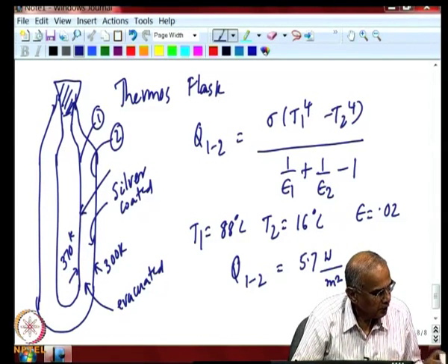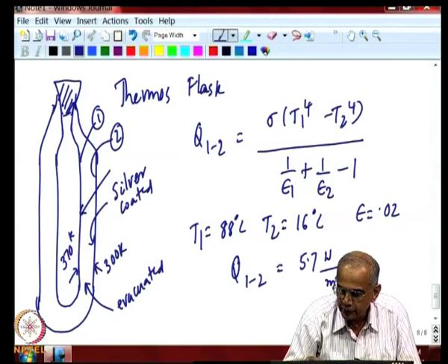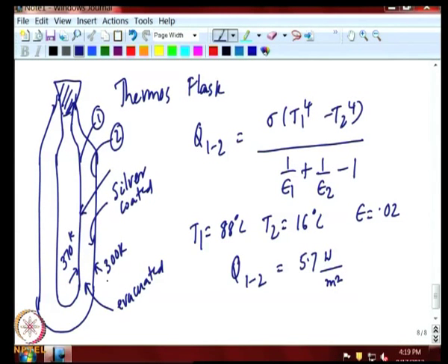And if you assume this is the only heat loss and you add a little bit of heat loss due to conduction, you will find for this heat loss the coffee should remain quite warm here for many days. But in reality, most of you have experienced that in a good Thermos Flask, the coffee remains hot only for maybe 8-9 hours. The main reason why our calculation is too optimistic is that the heat loss to the top, heat loss to the cap, which is very large.